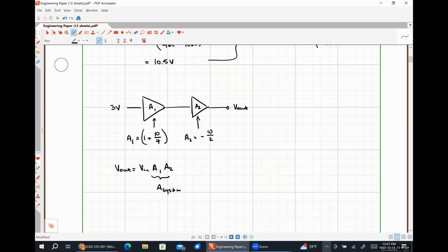So if we were going to cascade together negative feedback and non-negative feedback circuits, we really just need to understand what each stage is doing to understand how things are going to work, right? So for instance, if we fed a differencing amplifier into a comparator, that would be effectively us saying we want to make sure that the difference between two input signals doesn't exceed some arbitrary reference voltage or something like that. That's something that we might need to do in a control system or something, right?